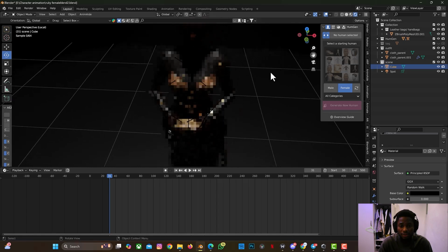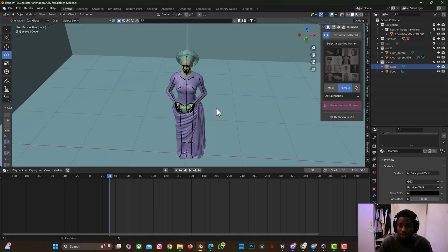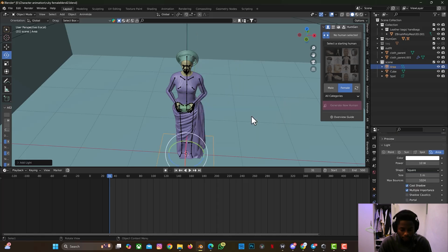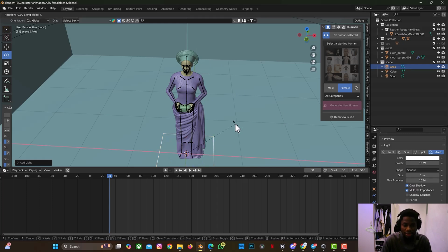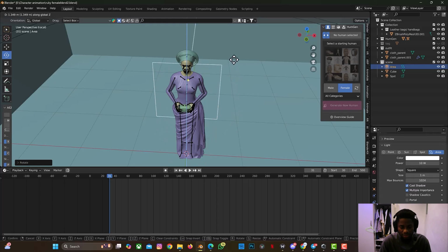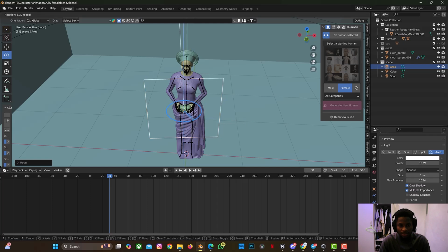And let me zoom back over. Let me just go back to this. It's quite slow in Cycles. So let's do Shift A, light, area light. I think RX90, GZ, GY. So I place the light at the front, but not exactly in front, just by the side, focusing on one part of the eye. And I rotated it a bit.